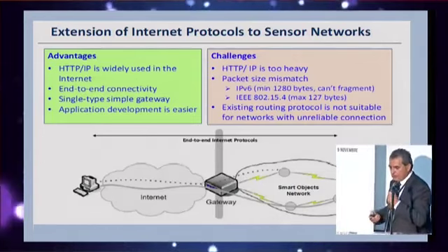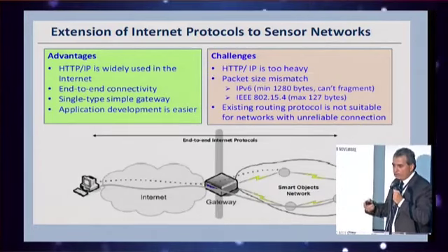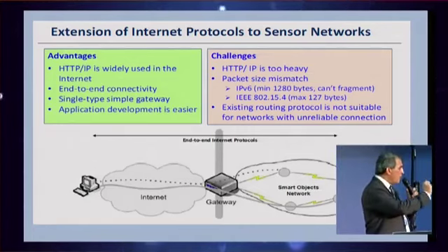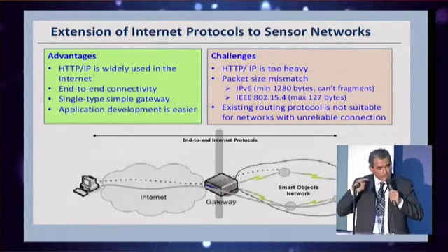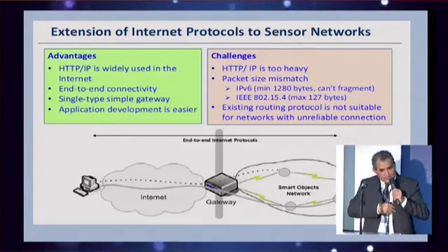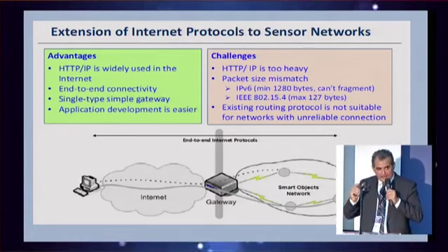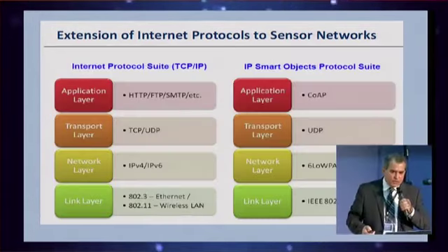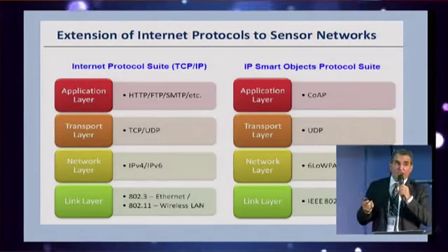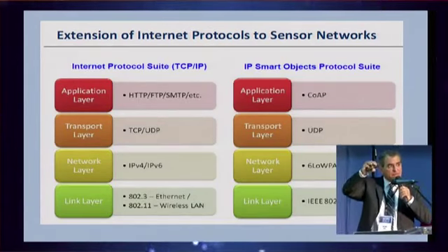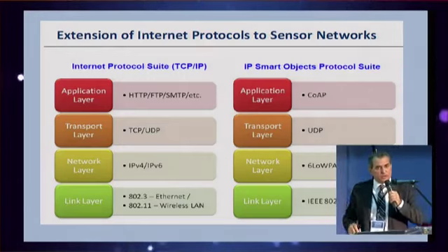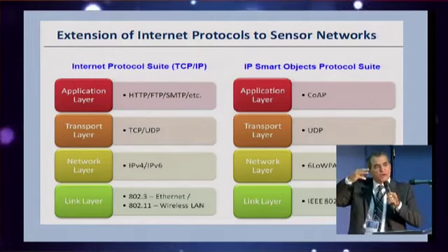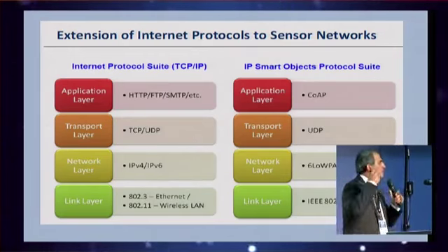Our previous system, as you know, follows HTTP. The challenge is HTTP is too heavy for a small device. While the small sensor has a processor, it has low RAM and low ROM. So HTTP, which we are currently using, couldn't work on those small devices, since they have very limited processing capability. So they shifted from HTTP to what we call the CoAP protocol. For all the application layers that we are going to use, instead of HTTP www.lille1.com, whatever, you will see coap://, and you write any IP of the sensors that you like just to get information.